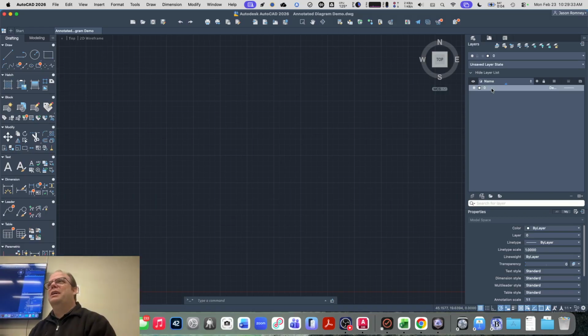And if you're all drawing on layer 0 in AutoCAD and you've done some styling on layer 0, then guess what happens? If you put your file into someone else's and yours is on layer 0, and they've also drawn on layer 0, then your layer 0 is going to inherit the properties of their layer 0, and all of your stuff's going to look different. Or vice versa.